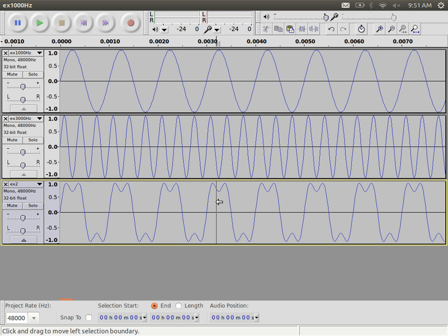We could add another component, a third component, and if we go back to the slides, we get a similar signal but slightly closer to a flat digital waveform. I've done the calculations before, so I won't do all those again. I'll load up the ones that I've calculated earlier. First, any questions? All I've done is try to show you the plots by adding two sine waves together.